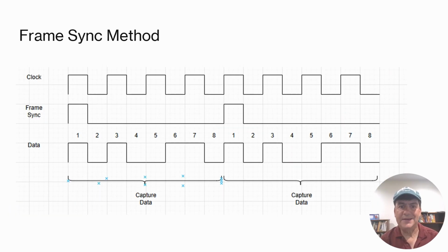Two ways to align the data. There are two ways to solve this problem. When the input data changes rapidly, comparable to the ADC sample rate, you'll need a frame sync signal to properly align the deserializer to the word boundary in the ADC serial stream. This relationship is shown in the diagram. When the ADC input signal changes slowly compared to the ADC sample clock and no frame sync signal is available, you're in luck. You can use bit slipping to align your deserializer so that the parallel 8-bit register captures the correct data. This video focuses on the second case, using bit slipping for alignment.